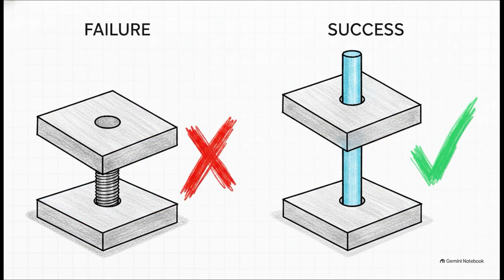Did you guess it? The answer is only the one with the projected zone. Literally, if you skip the projected tolerance zone on a thick threaded stack, you can sail right through your standard CMM inspection and still completely fail final assembly. It's wild. This failure mode pops up exactly when the mating part's clearance holes are just too tight to absorb that unmonitored thread tilt we talked about earlier. By forcing your functional gauges to simulate the pin at its full, real-world projected height, that little circled P guarantees the tilt is caught way before the part ever leaves the machine shop.